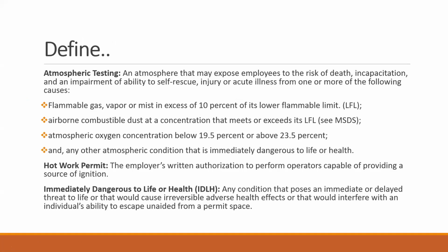Atmospheric testing. What is atmospheric testing? Atmospheric testing is one of the major parts of confined space work. Before entering the confined space, we need to perform atmospheric testing. This can include flammable gas, vapor or mist in excess of 10% of its lower flammable limit, airborne combustible dust at a concentration that meets or exceeds its LFL, which is the lower flammable limit, and atmospheric oxygen concentration below 19.5 and above 23.5. So these are all hazardous conditions, and any other atmospheric condition that is immediately dangerous to life and health.